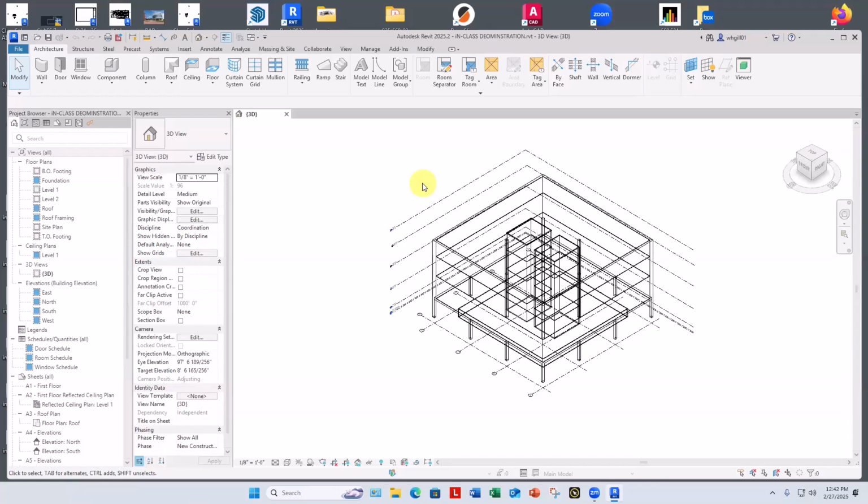We know the main one for the first floor is 15 foot 8 inches, that tiny tile ceiling for the first floor. And the other ones for the upstairs are just lay-in 2 by 2 foot acoustic ceiling tile, which we'll get close with. And then finally, we'll be putting the storefront windows, a section of them in here, and copying them up just with copy aligned to selected levels. So most of the stuff we only have to do once, and then we can just match properties or copy and create the rest of it. So it's pretty friendly building that way, very regular.